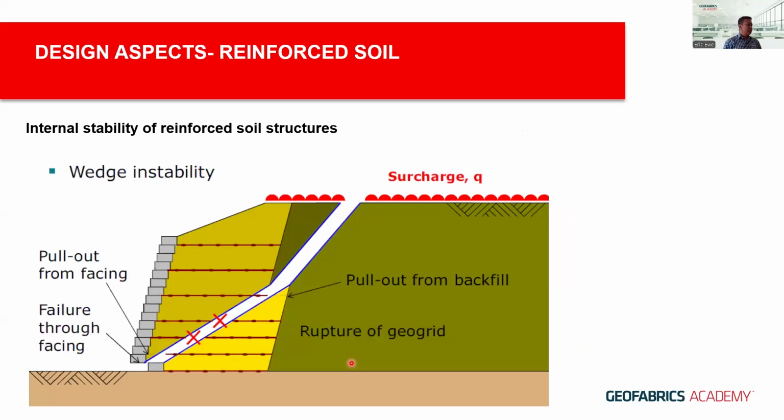Now, when it comes to design of reinforced soil structures, just one quick slide to talk about internal stability. In short, it comes down to determining the layout of the geogrid reinforcement, its spacings and length, so that they are strong enough not to rupture under the soil weight or surcharge loading, external loading.